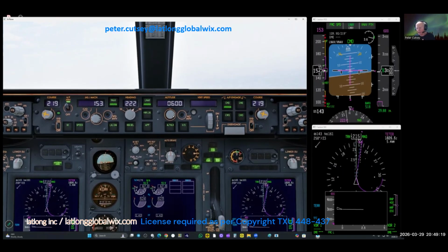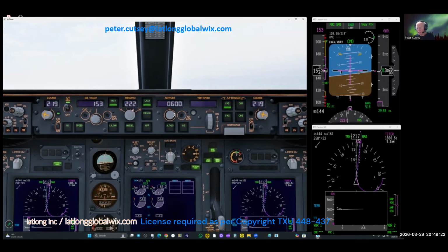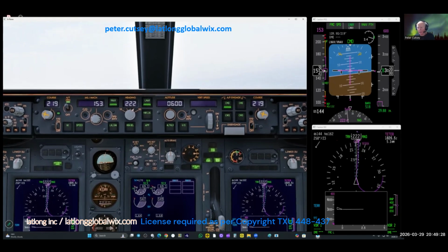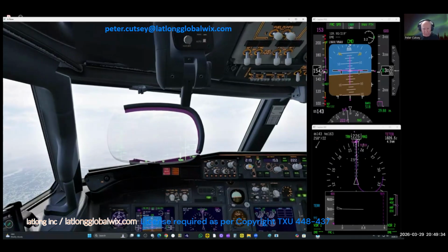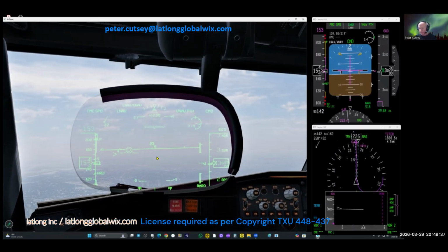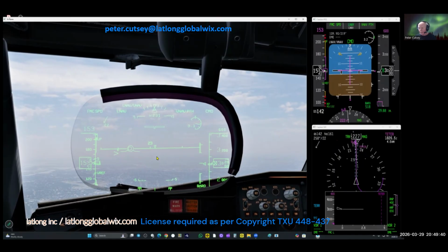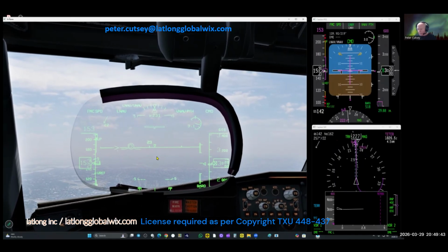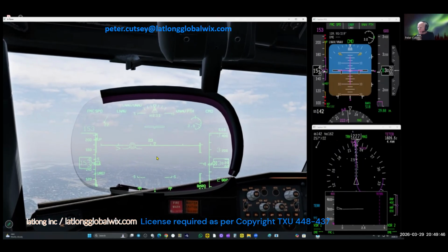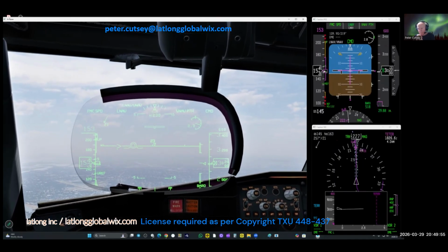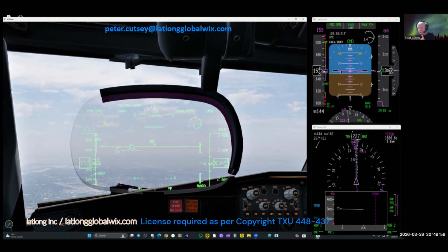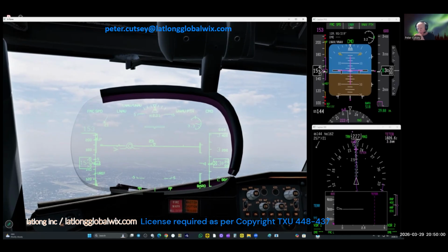So these items are basically done 2 nautical miles before the descent. Here's our path, vertical path, all set on the nav display. So as I mentioned before, this would be gear down, flaps 15, speed brakes armed, would come just 2 nautical miles to Teterboro.